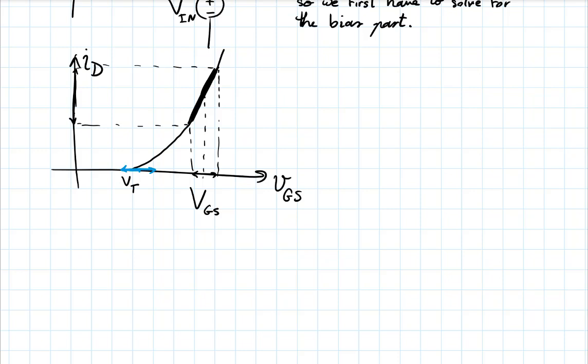And the answer for this is one has to be very careful. If the change, the small signal change that you apply, takes your transistor from one mode of operation, which is on and saturation in this case, to another mode, which is off, the equation for the transistor literally changes, right? The current goes from a quadratic behavior to 0, right? And therefore, you cannot describe this problem with just a small signal change. You can describe maybe the positive half of it with a small signal change, but not with the negative half.